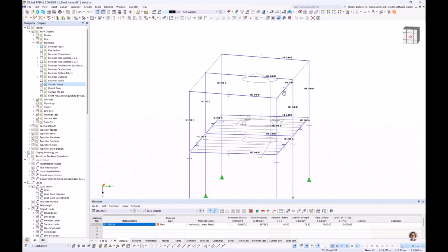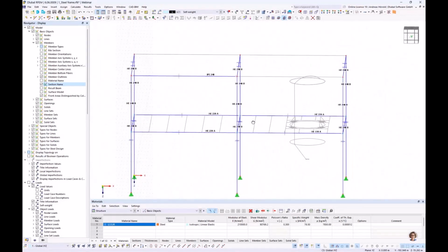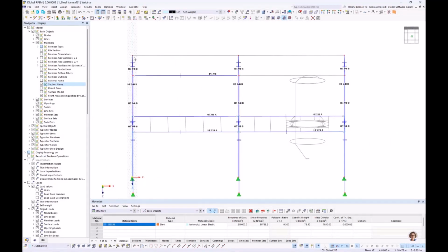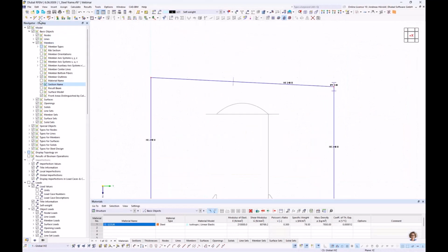That's why I change the work plane to YZ above. You can see the work plane. So view in X direction. And I create a line, a help line in that case. Left above, new line.